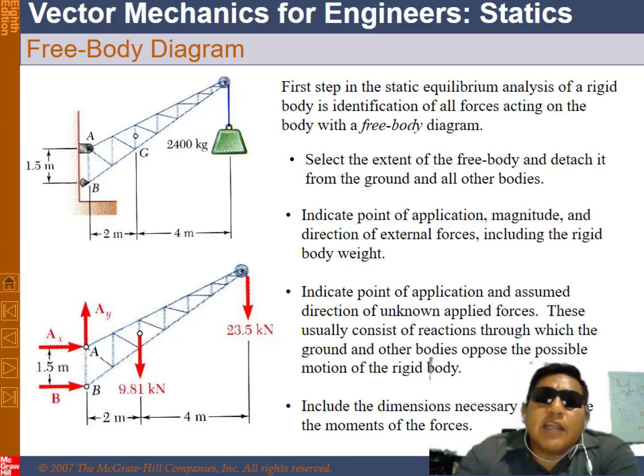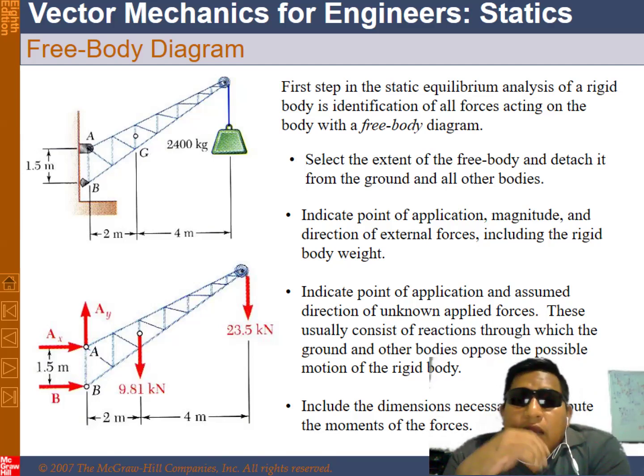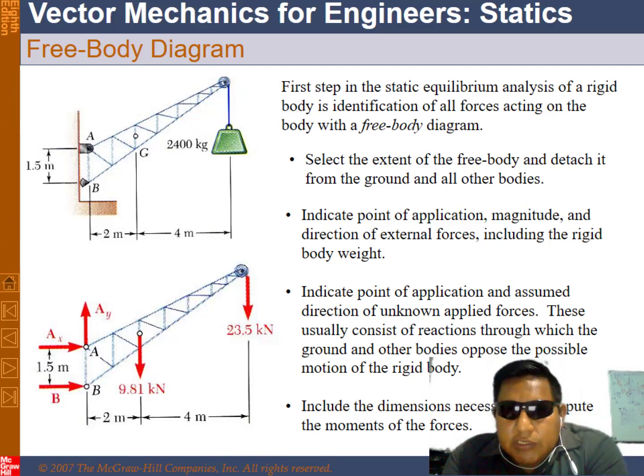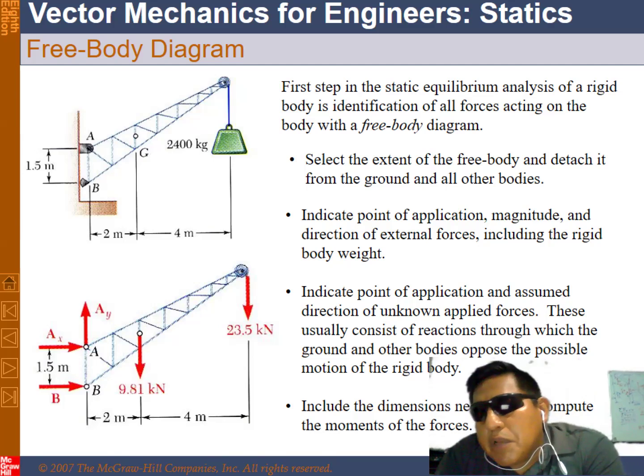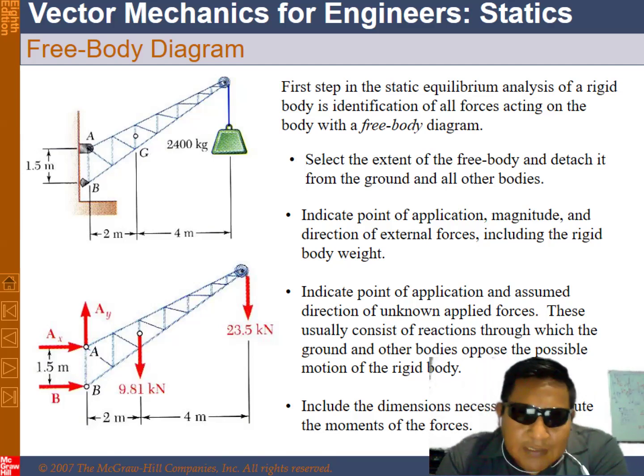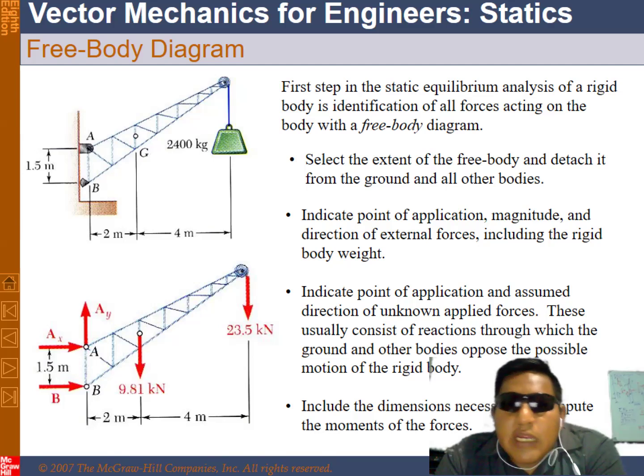For the static equilibrium analysis of the rigid body, the first step is identification of all forces acting on the body with the free body diagram. Select the extent of the free body and detach it from the ground and other bodies. Indicate points of application, magnitude, and direction of external forces, including the rigid body weight.